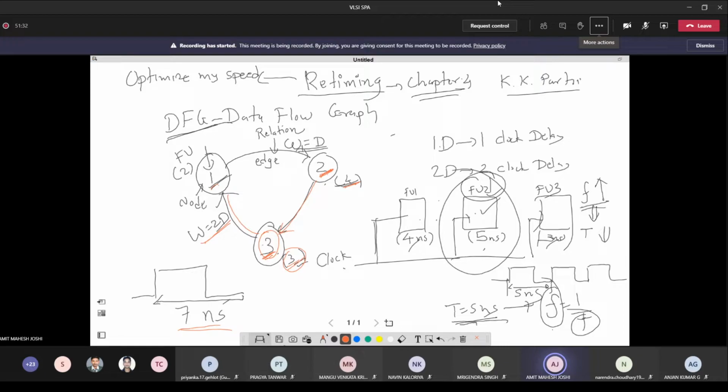If there is a difference of the clock, then we do not have to worry about it. If something needs to be completed within the same clock cycle, then we need to worry, because that is reflected in the minimum period we require for our clock cycle.